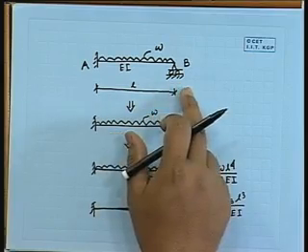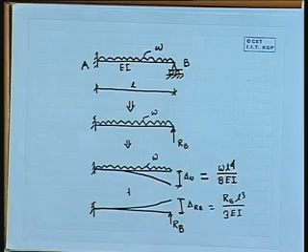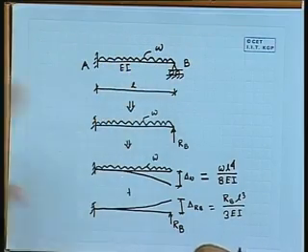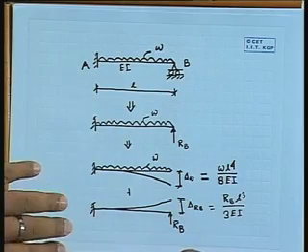So it will be a simply supported beam, fully loaded, plus an end moment. So there due to the fully distributed load there should be a slope, and due to that moment slope will be in the reverse side, right. So the vertical load will try to make a slope like this, and this moment will give a slope in a reverse manner, and it should be equal and opposite, because it is a fixed support, so slope should be equal to 0.